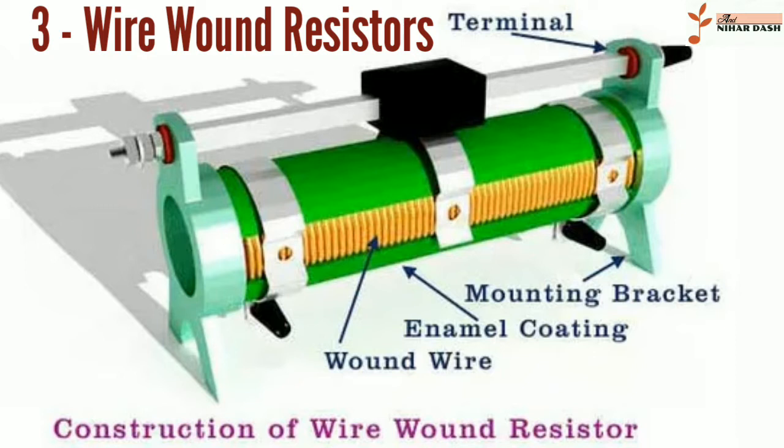The assembly is protected with a layer of paint, molded plastic, or an enamel coating baked at high temperature. These resistors are designed to withstand unusually high temperatures of up to 450 degrees C. Wire leads in low-power wire-wound resistors are usually between 0.6 and 0.8 mm in diameter and tinned for ease of soldering. For higher power wire-wound resistors, either a ceramic outer case or an aluminum outer case on top of an insulating layer is used.